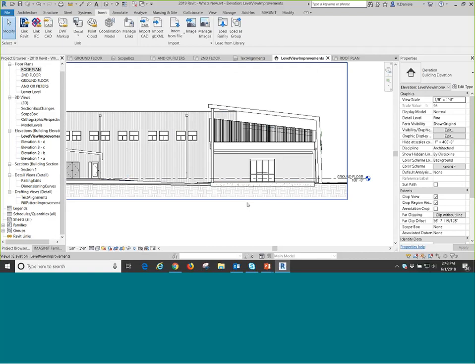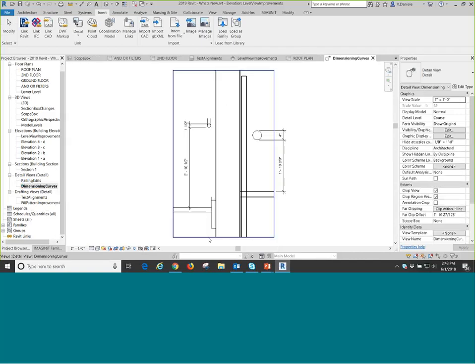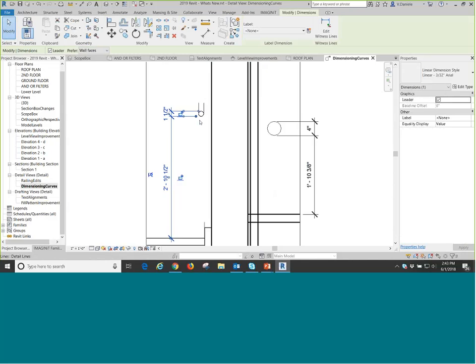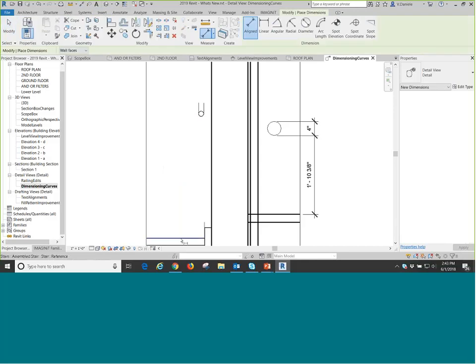Okay, let me go through this stuff kind of quickly. I know I only have a few minutes before Q&A, so for creating, we're kind of in the create phase now. One of the feature enhancements here, I'm not going to go through the slides, I'll just keep it in Revit, but one thing that we can do now in section views, elevations, and plans is snap to and dimension to curved objects. So instead of trying to create reference planes or invisible lines to dimension to off of objects, you can now dimension directly to curves.